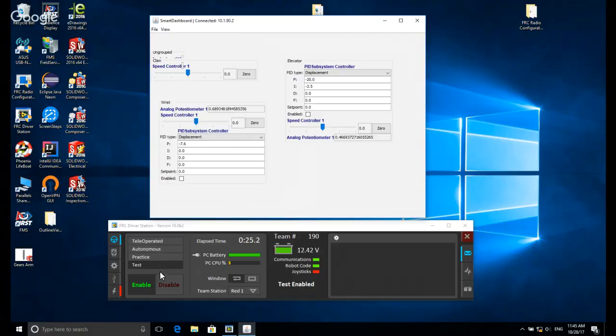Okay, so I'll just do it again. I enabled test mode on the robot, and without writing any code except using the RobotBuilder code, we get this, which is the elevator subsystem and the wrist subsystem and the claw all on the dashboard. What you can do is it has these nice sliders, so you can drag the sliders around and the robot will move without writing any code. And this code is always available to you.